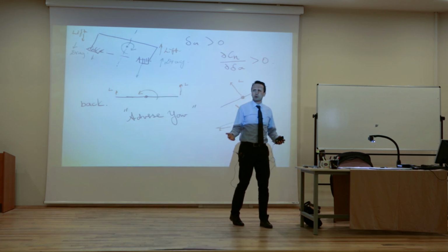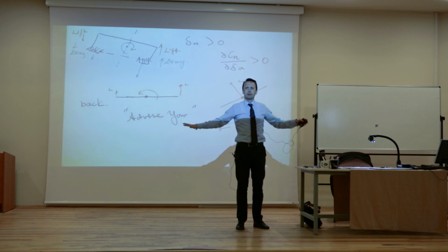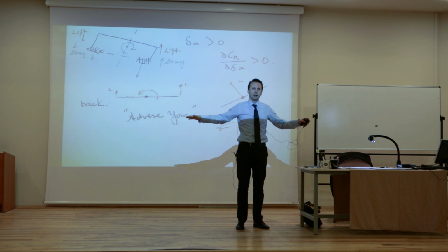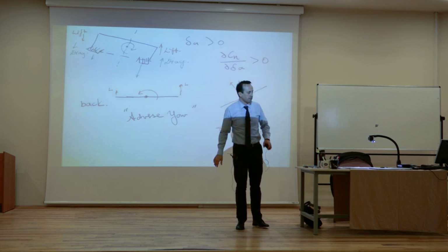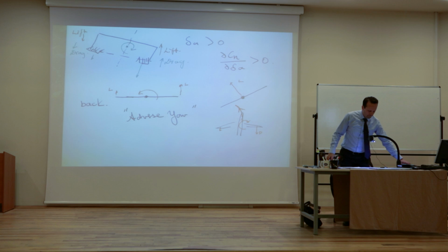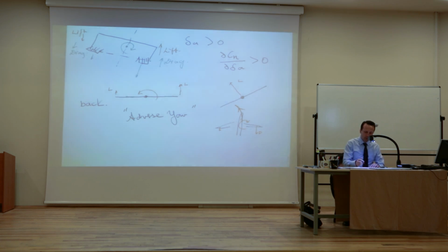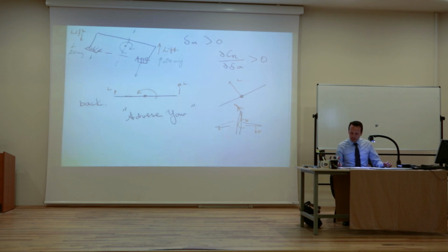For most passenger airplanes, the rotation is really slow. It's a little bit of a change in the aileron and you start rotating like that. You see? Okay, so that's adverse yaw. So how do you get rid of adverse yaw? What can you do? If you have a really big wing and adverse yaw is really a problem. As I said, for most airplanes, it's not a big problem if you make these rather slow turns. But if it's a really big problem, what can you do?